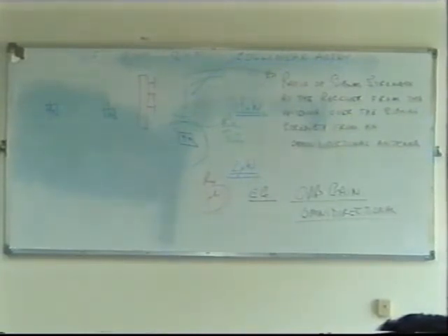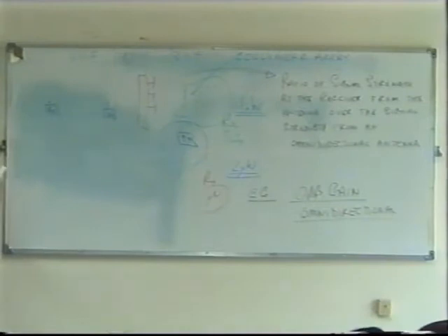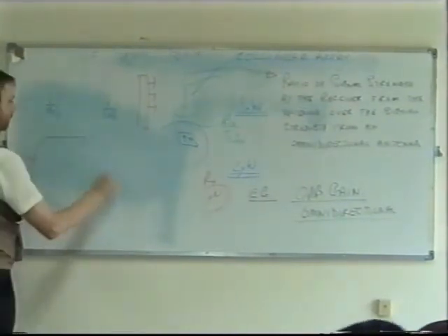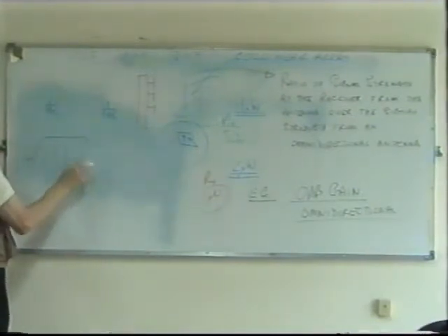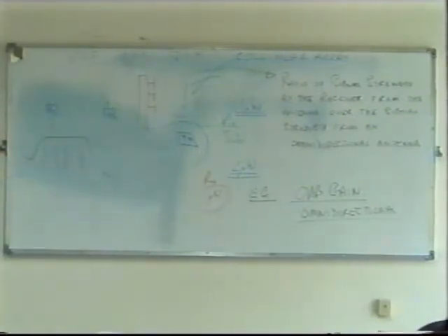Now, when we do tuned circuits, I'm going to cover tuned circuits later, inductor capacitance tuned circuits, reactance and things like that, we can talk about bandwidth. And it depends on the bandwidth of the antenna. An antenna is designed to operate over certain frequencies. Not just at one frequency, it's a band of frequencies. So we talk about bandwidth. And providing the channels that you're transmitting on fall within the bandwidth of the antenna, no problem, it's treated as one signal. Does that answer your question?